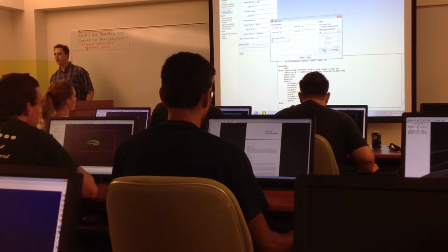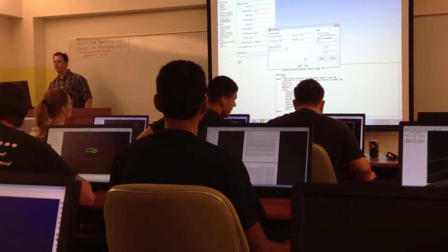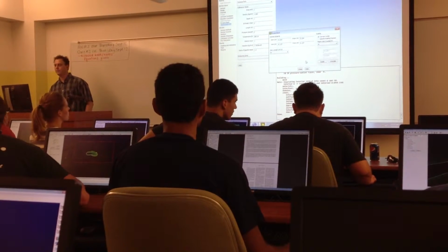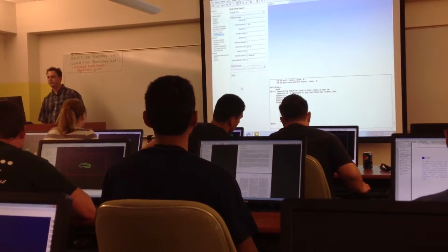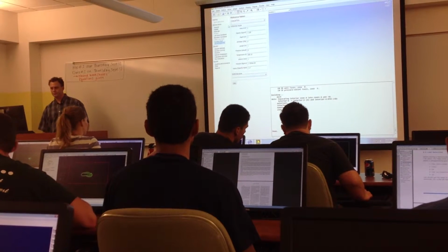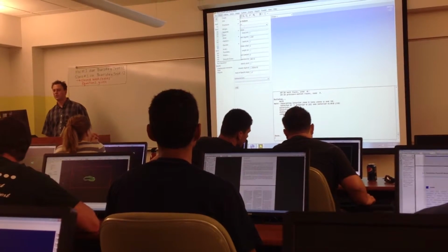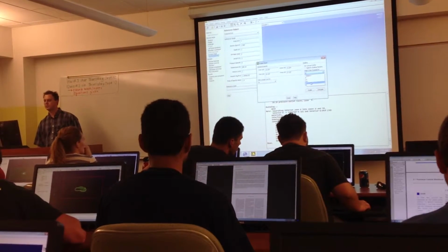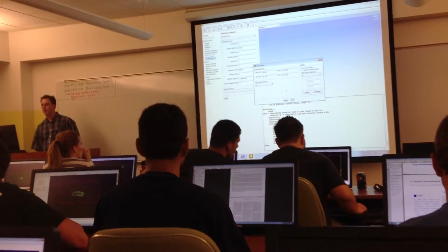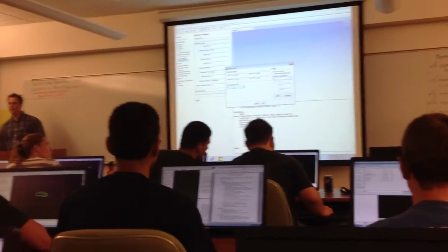And then you can press scale, and everything will end up scaled. The grid should be scaled now. What did you do to do that? Yeah, mesh, scale. Mesh was created in, make sure it's in inches. I'm leaving view length unit in meters.